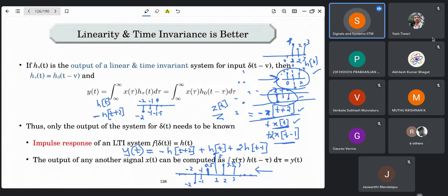So when you flip the impulse response, what does it actually do? If this is your impulse response, when you feed in an impulse as the input, you get exactly this as the output. So the flipping is essentially to ensure that you add the corresponding time outputs. As you can see here, we added up the signals that came at exactly 0, and something exactly at 1.